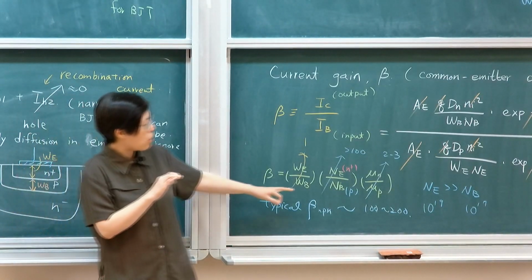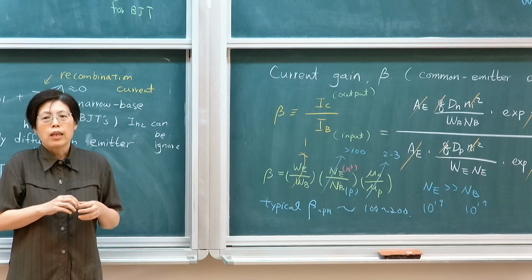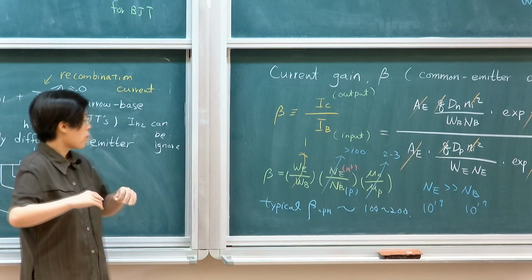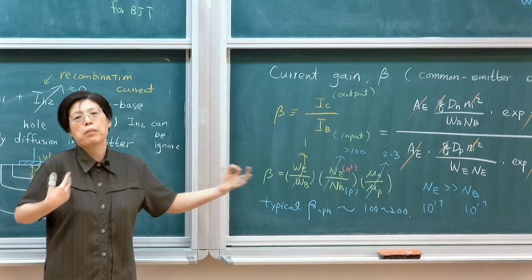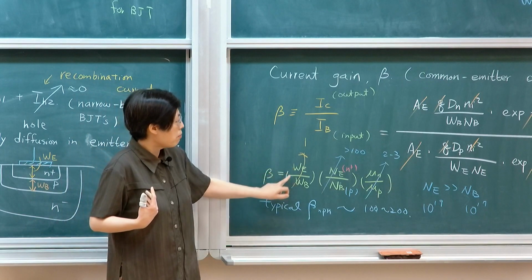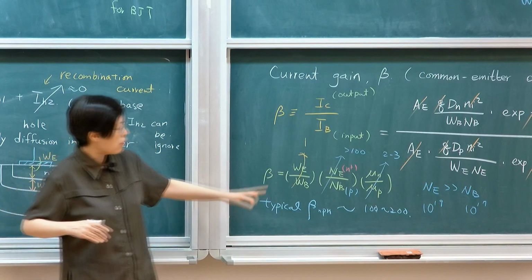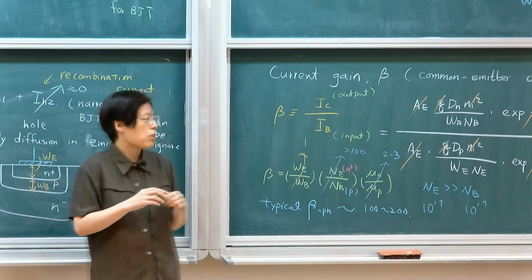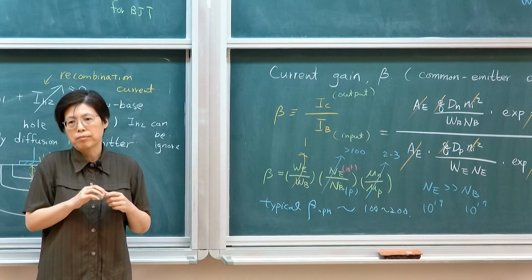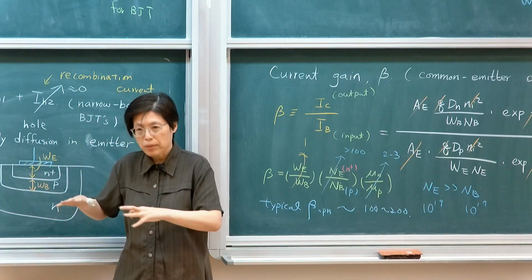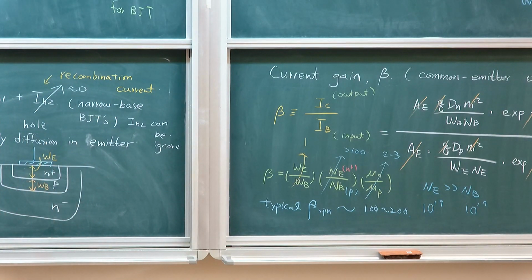But just to look at this equation, if you think about it, if I'm having the same structure, the same doping level, it just becomes P plus N, and then the same base dimension, base emitter dimension ratio, what do you expect the beta will be? So if the structure is the same, it just becomes PNP.